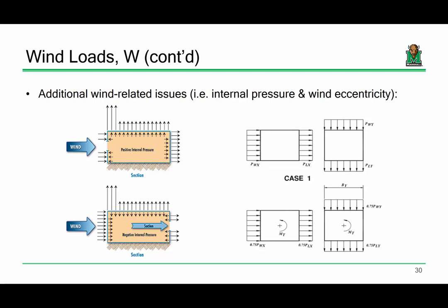That can change not only the amount of wind pressure that goes onto your frame, but one of the other components of wind design, which is a really big avenue of wind engineering that we're not even talking about, is how to design for components and cladding. Take this building. There's a curtain wall of brick and windows and whatnot that surrounds the building, and that is attached to the frame. Well, those attachments and the wall itself have to be able to withstand those wind forces, and being able to properly do that is a task in and of itself.